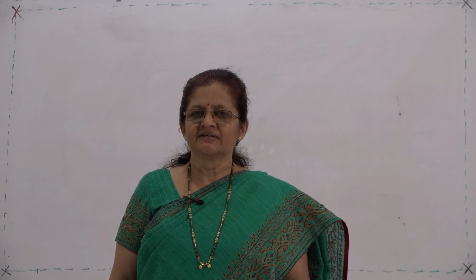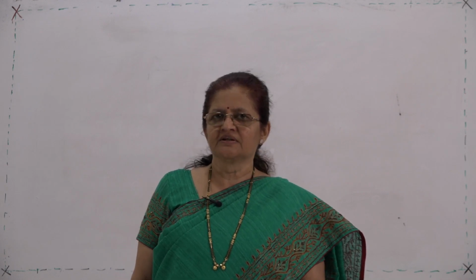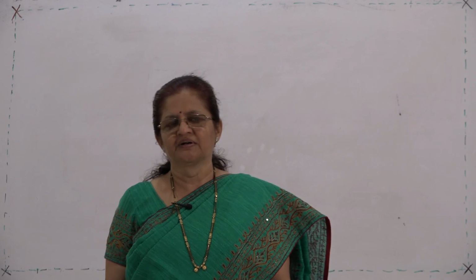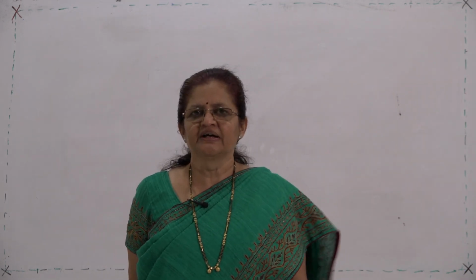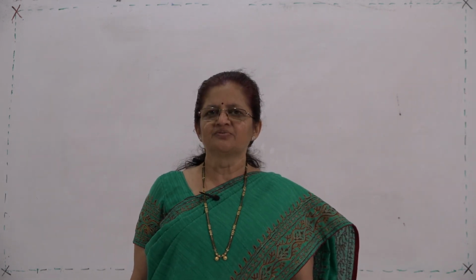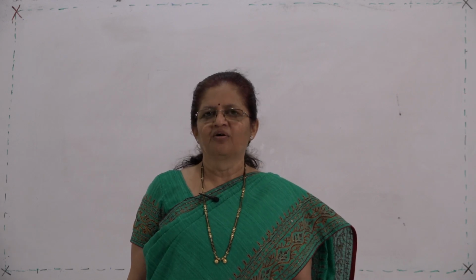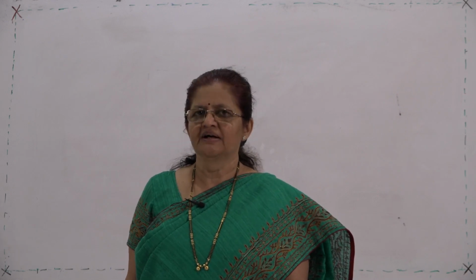Welcome all for this lecture. We are considering Bode plots. In the previous lecture, we have seen that if the transfer function is given in the time constant form, the main advantage we get in the Bode plot is that, as we are taking logarithm, all multiplicative terms become additive.